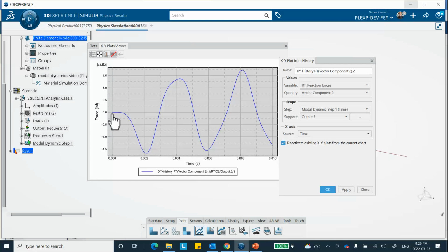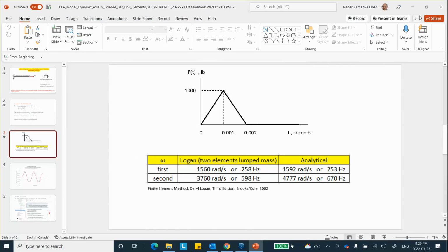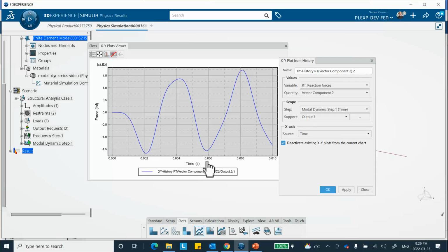It goes from 0 to roughly 1500, 1600. Now, notice that clearly there is a dynamic effect here. First of all, because you can see that the load on the top and the bottom is not the 1,000 that we apply. It's more than that or less than that, either way, if you look at the positive and negative. And that means that there's a dynamic effect.